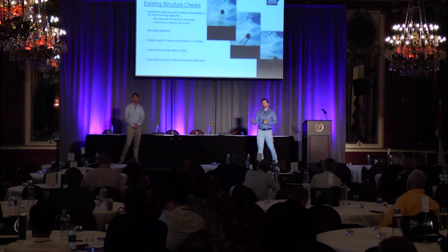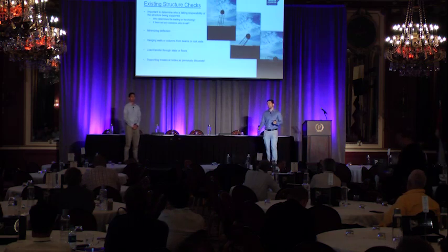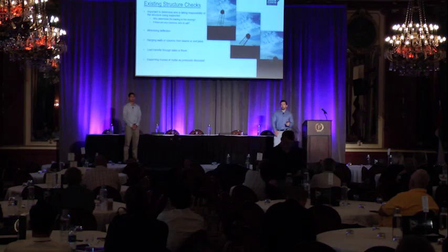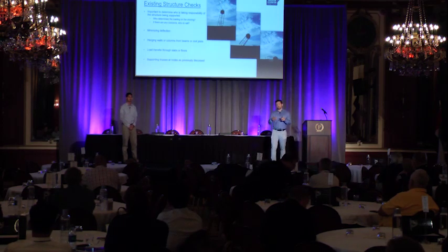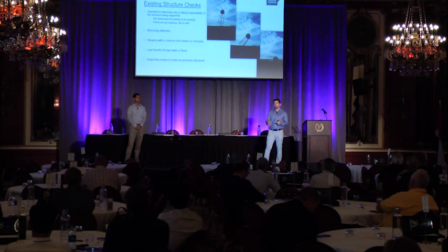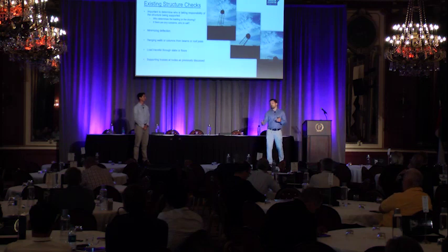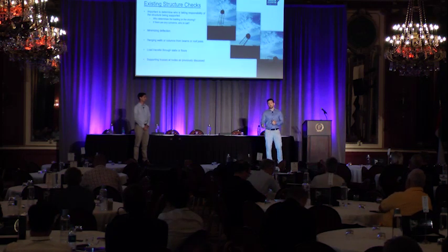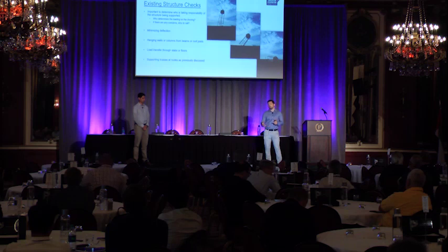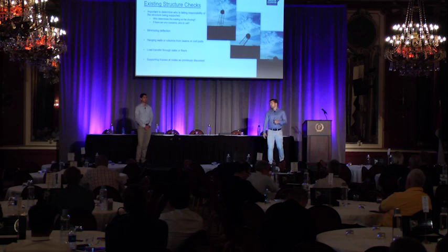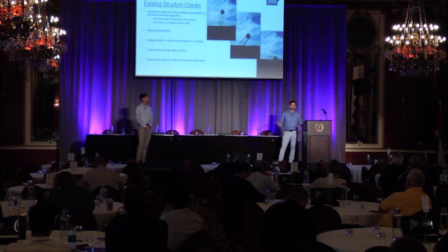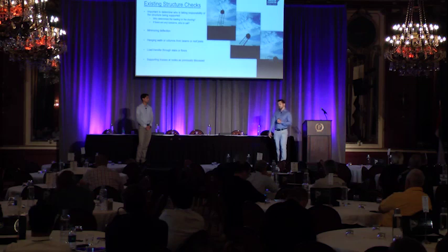More often than not, there's a structural engineer of record on the project who's designing the retrofit or is more familiar with the existing structure, who can take the shoring design and look at the structure and make sure it's adequate to be supported at that location. And you definitely want to have this conversation, because if they do want to put it back on you, a lot of times it's a lot more expensive and time-consuming to check the structure versus actually producing a structural shoring design. So being able to account for that time and additional cost up front is very important, because if it comes up in the middle of the project, a lot of times there's fingers pointing on who's responsible for taking this cost.